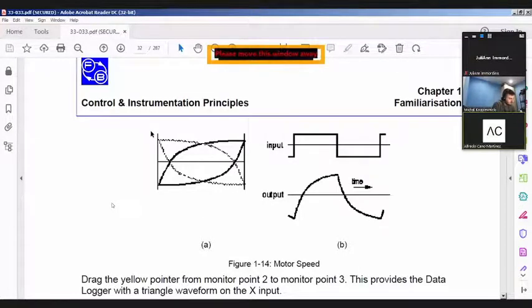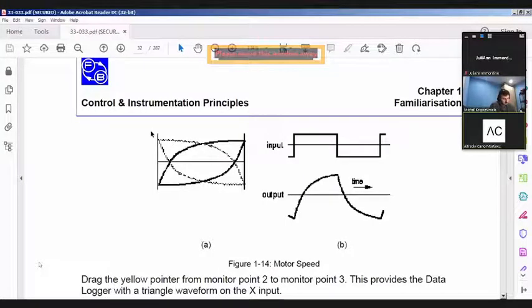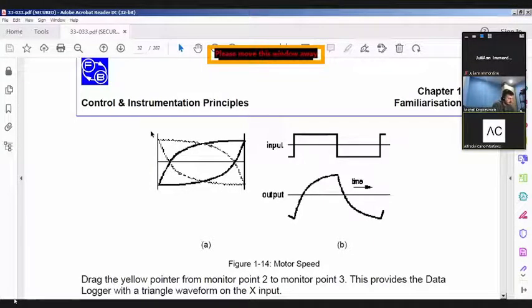Let me give you an example. You may agree that, for example, the cruising system, you drive cars, right? You know what a cruise control is? So you may agree that the control system tailored for this cruise control should be somehow different than the control for an elevator, right? I mean, these two systems do not really have the same kind of dynamics, but you can actually use PID in both of these, but you have to really tune it to your application, right? Because sometimes, for example, the cruise control, you want to have KI, the integral.